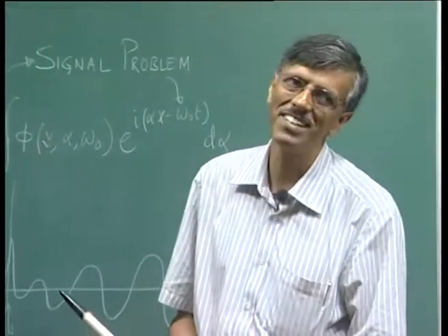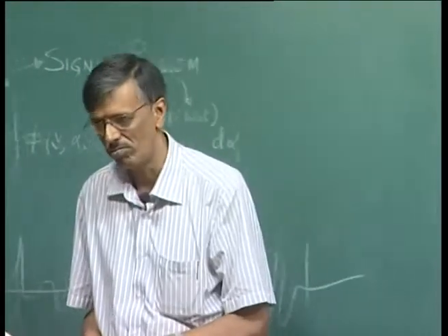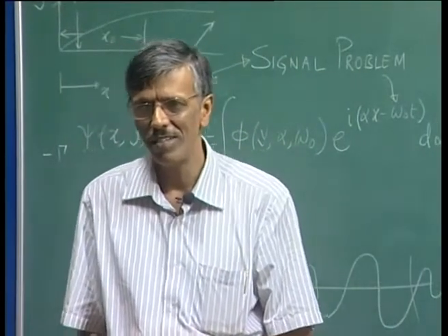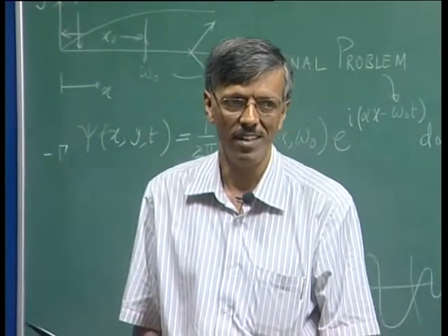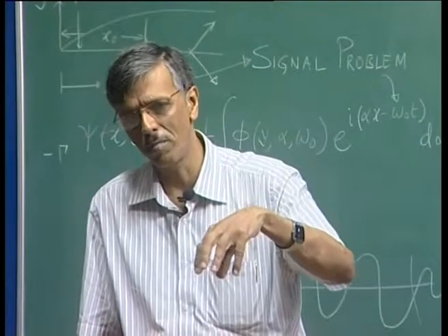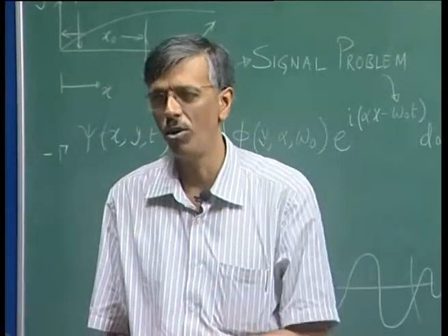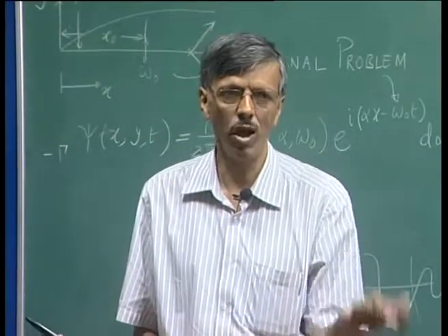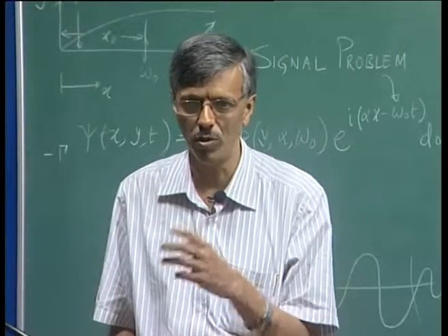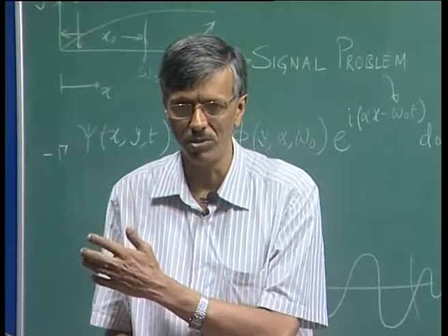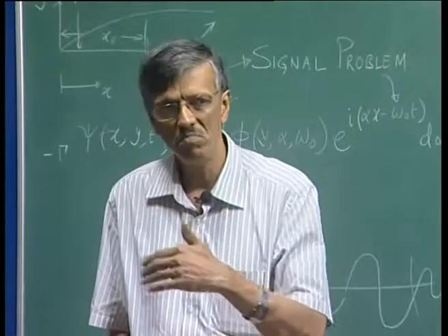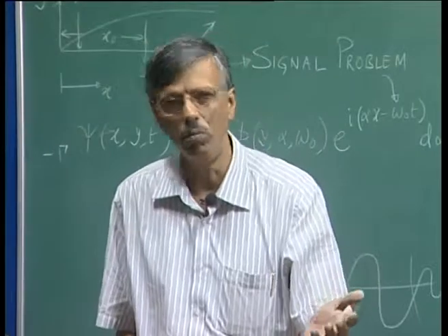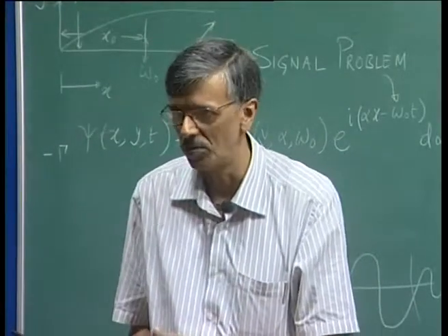I did the experiment and it is not there. But what G.I. Taylor overlooked, or no one pointed out to him at that point in time, is the frequency. He used a sort of a circular patch which was vibrated at a very low frequency, less than 5 hertz. Whereas Tollmien and Schlichting's calculation, the stability curves, show the waves to be in the moderate range, say more than 10 hertz or so.